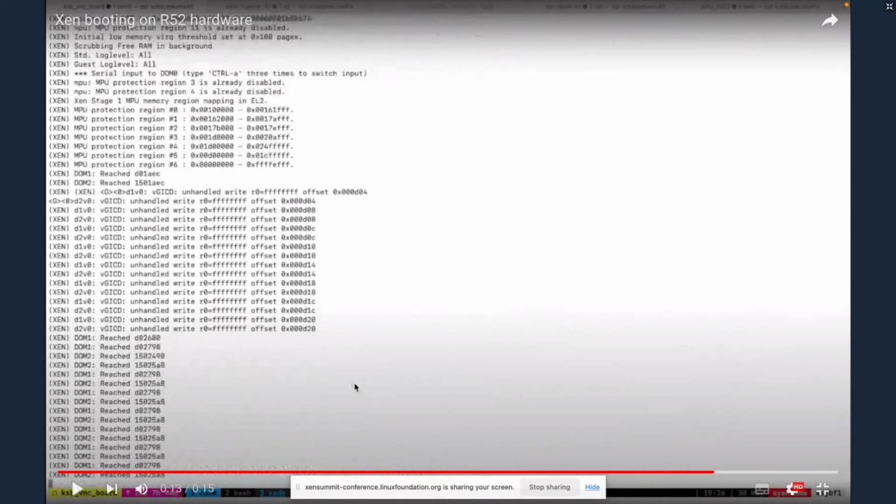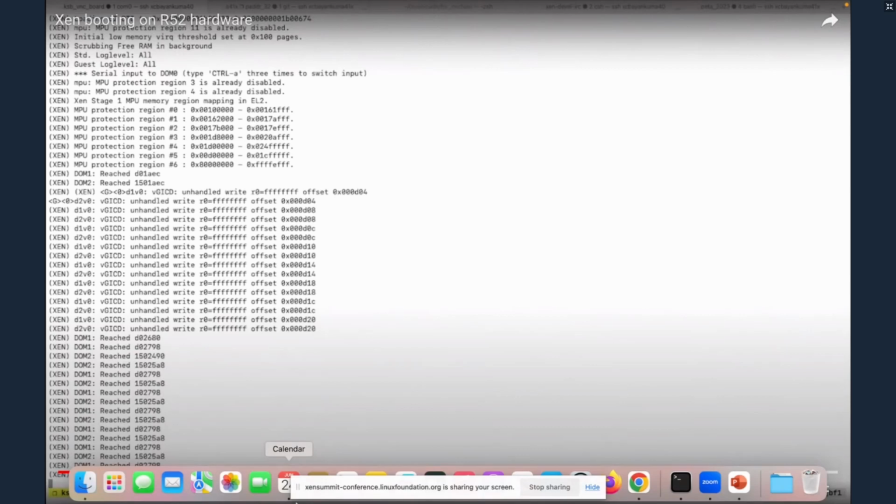And here you could see that it is trying to run the two DomUs. So what I have done is I've added the hypercalls in the TTC interrupt handlers for the Zephyr, just to show that the interrupts are getting invoked. And now I'll go back to the presentation.